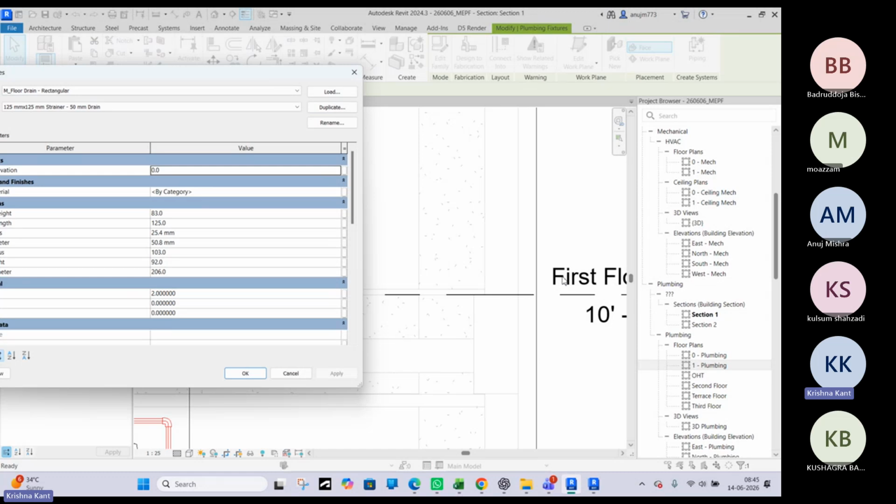So we have to provide more diameter so that it can easily handle the water pressure when so much water accumulates. Also, in a high-rise building the pressure will jump so much from the height, like when the drain water is coming from the 50th floor or maybe the 75th floor, the water is at very high pressure. So actually in every 7 to 10 floors there is a pressure wall.